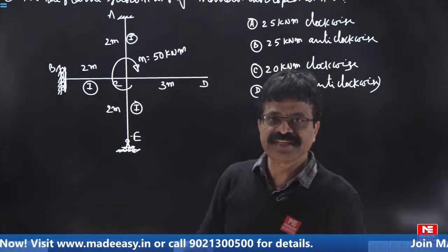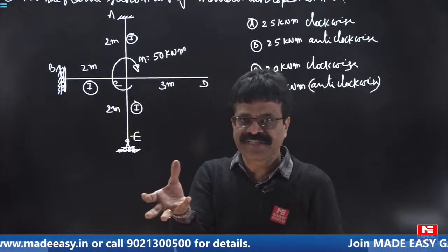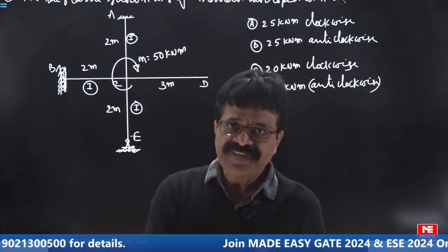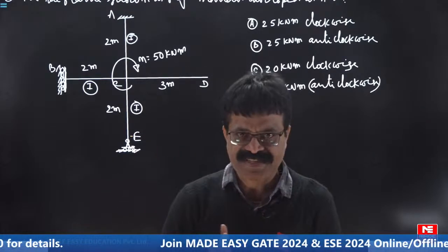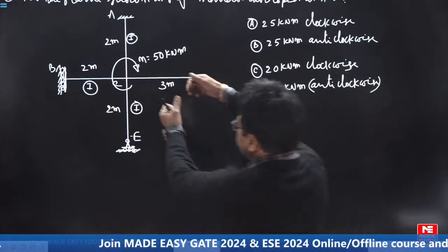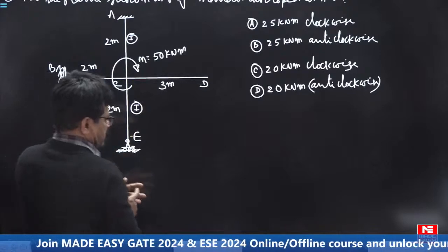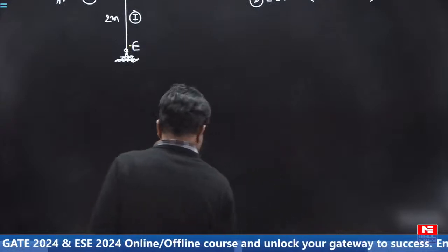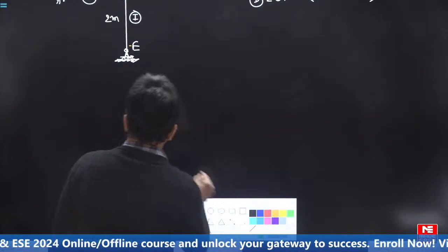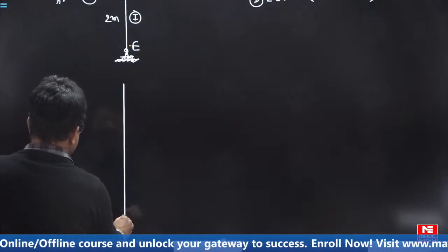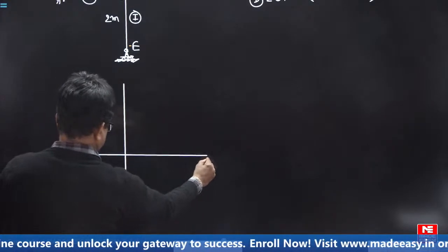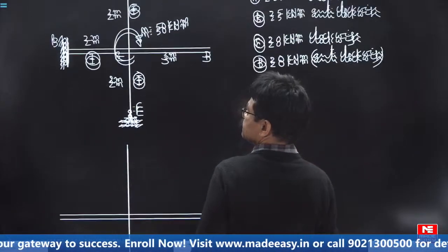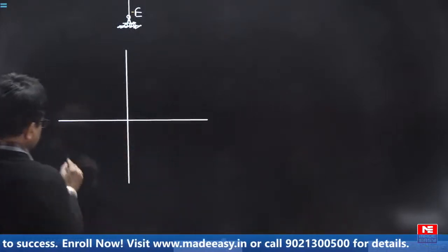But after studying that also, you must apply first the rotation, see the deflection profile of the individual members. Those deflection profiles will tell us what is the relative stiffness. Okay? So when I hold this and try to rotate, the deflection profile of the members will be something like this. I am showing them here. Okay, there is a guided roller support here.